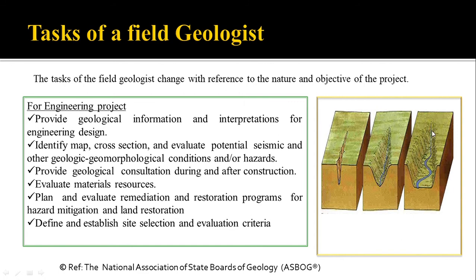The river does not have sufficient water. As well, the river may carry a large amount of sediment. So they have to select a location where it is in the mature stage. Not only that, the valley should be narrow, because if it is a broad valley, then they need a larger amount of construction material to construct a dam. Whereas in this location the valley is quite narrow compared to that, so the material required for construction is much less. So the geologists have to establish the site for the construction of the dam, as an example.